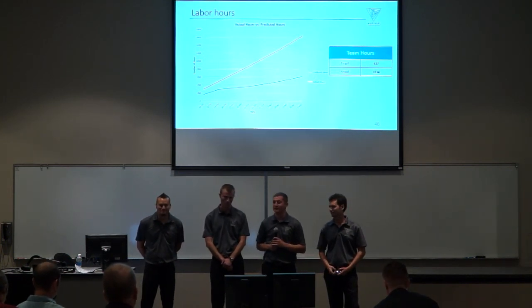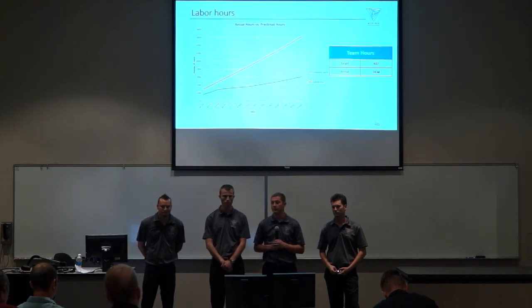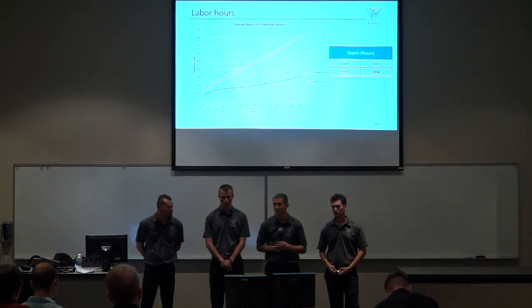We looked at temperatures of combustion and things like that, just to see what temperatures we could expect in there. And then we looked at the melting temperature of aluminum, and I don't remember them off the top of my head, but it was a safe range. I don't know how long we could go before it would start affecting it, just because of long-term heat transfer, but the temperatures themselves were within safe ranges.